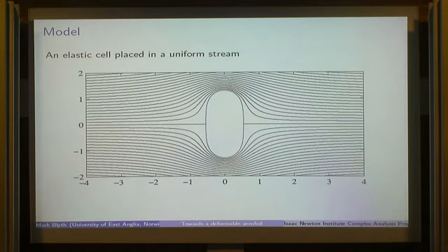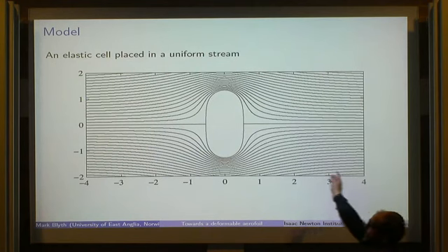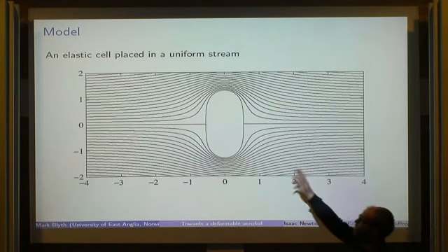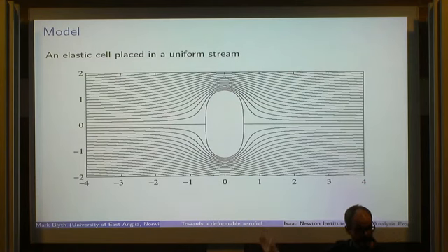So there's going to be two effects for the deformation here. The first one is that there might be a pressure difference between the pressure at infinity and the pressure in the interior. So we'll set that as a parameter. And the second is the effect of the flow. Okay, so the flow, as the fluid goes past the balloon, everything I'm going to talk about is inviscid, by the way, as well. And almost all of it is inviscid and irrotational.